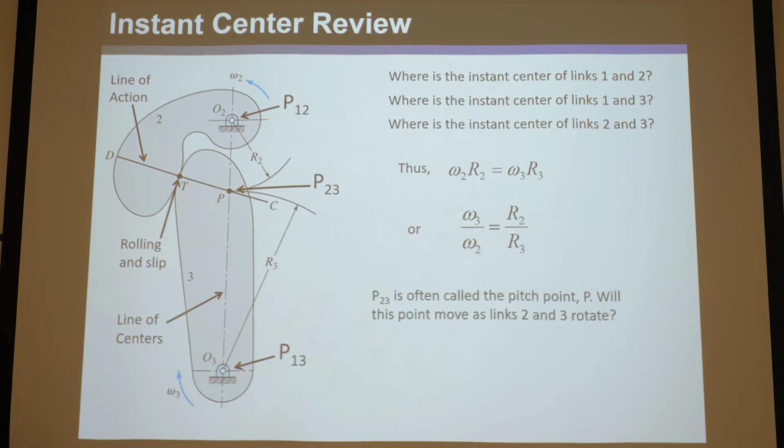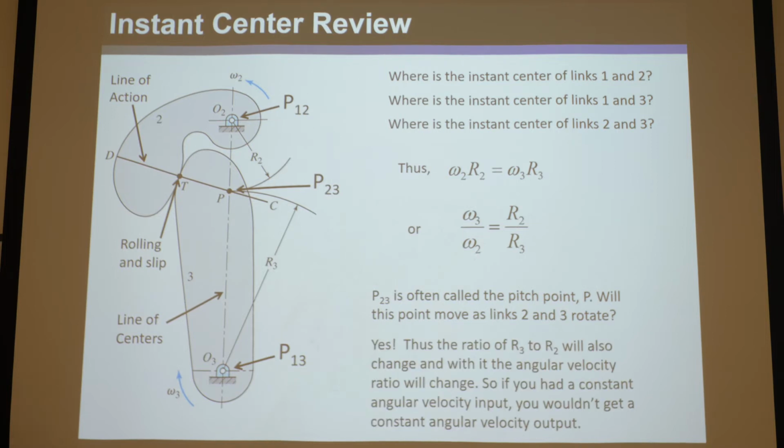By the way, P23 is often called the pitch point, P, another P. And the question is, will this pitch point move as links 2 and 3 rotate? I want you to think about it first of all, but you can put me on pause. But anyway, assuming you take me off pause here, the answer is it will move.